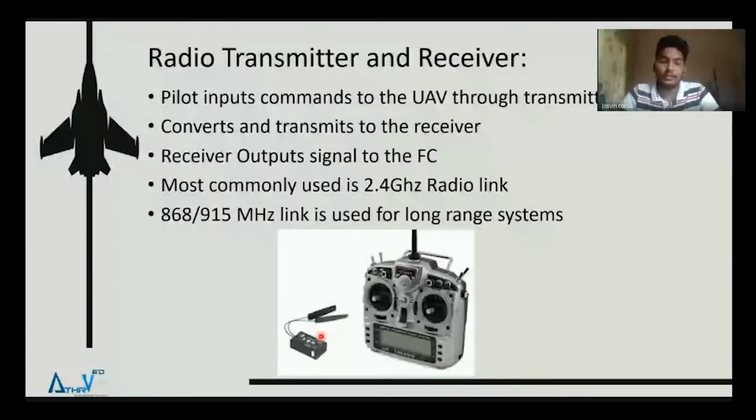And you have to take this into consideration, because some FCs will only take PWM signals or PPM signals or S-bus signals. So while determining what radio you need to take, you should also look into whether the output from the receiver is supported by the FC.